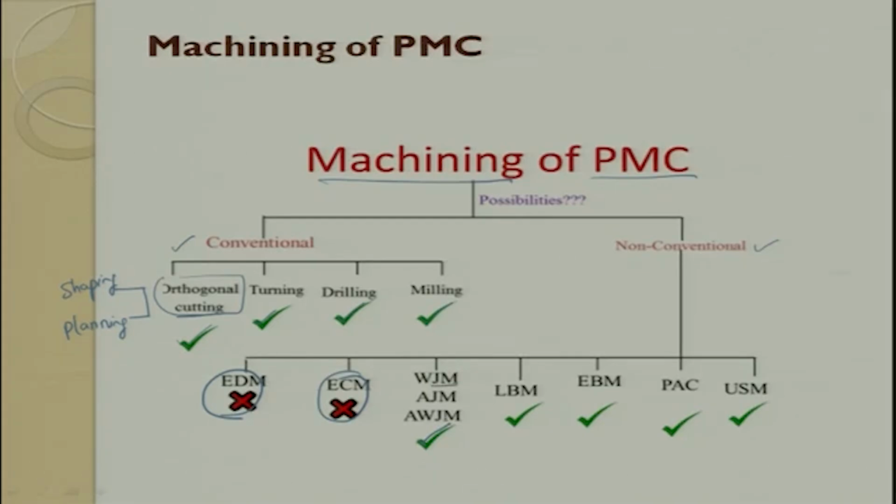So, in jet machining process what we use is a jet of very high pressure, and this pressure is passed through a nozzle and then exactly focused at the workpiece. This nozzle is moved relative to the workpiece and generates a geometry. Because of the high pressure, this is used for cutting the workpiece. So, the jet can be made out of water, the jet can be made out of abrasive. The abrasives are predominantly ceramic, and these are nothing but particulates.